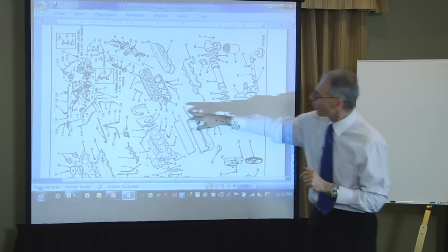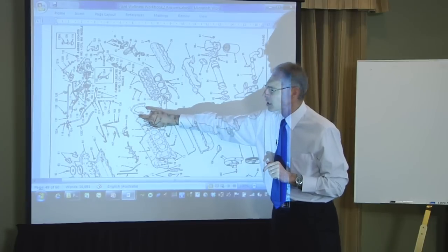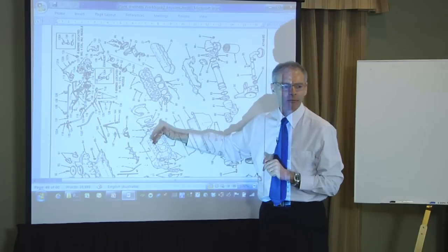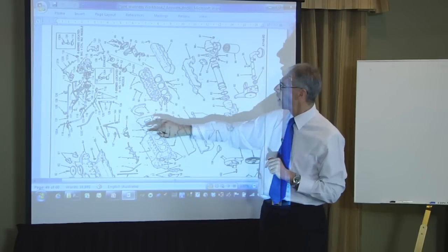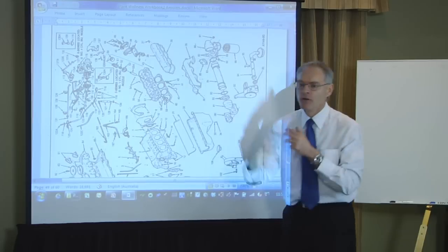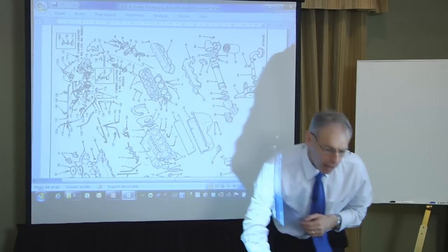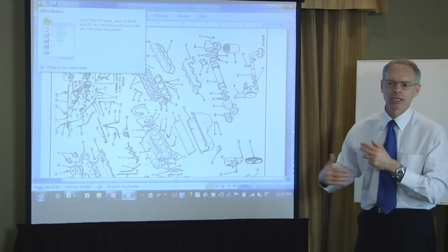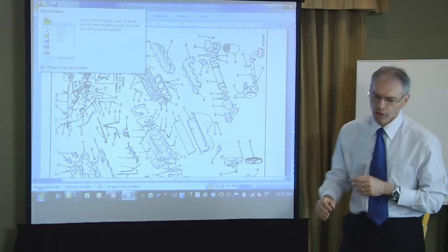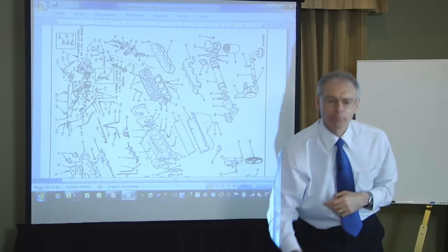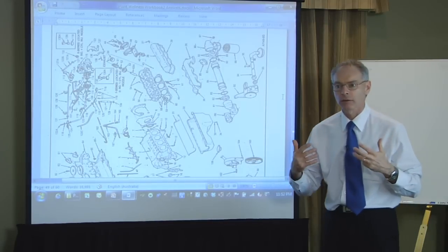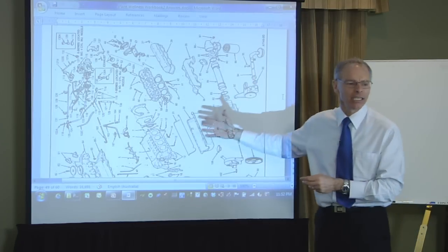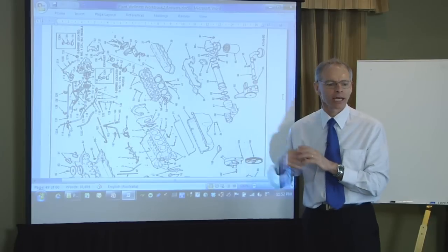So I'm not going to worry too much about this issue here. That's simply bolted on there. The procedure needs to be written so that this is properly done, but this won't be under stress. That part will be under stress. Any moving parts, any parts that rotate, the pump internals are going to be under stress because they're being used. I'm not going to do every single part just because I can. I'm going to do the parts where the risk is to the machine. So out of 200 parts, there might be 24 in the end that I will actually analyse in some detail.